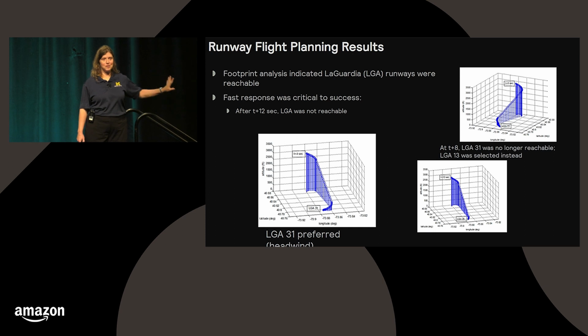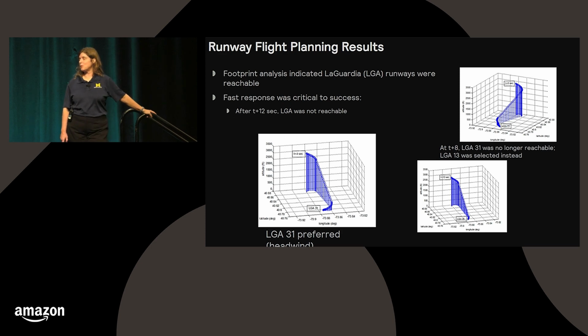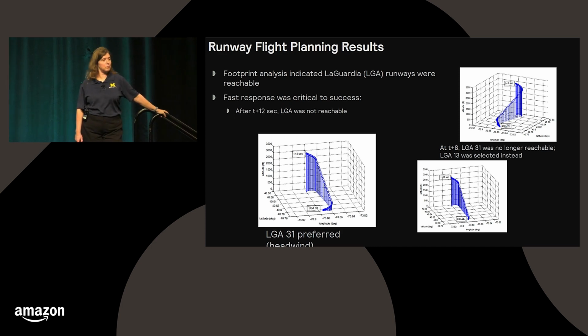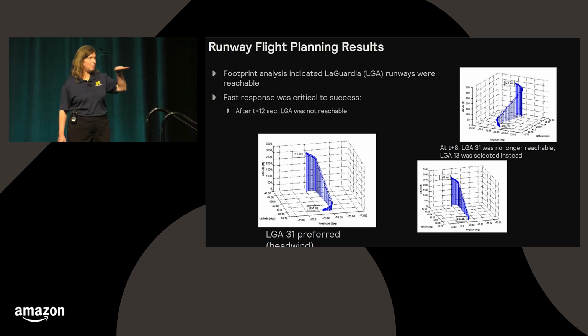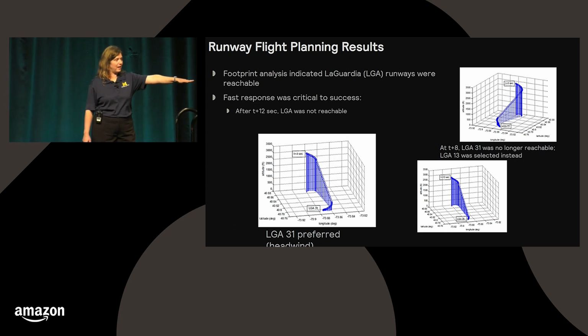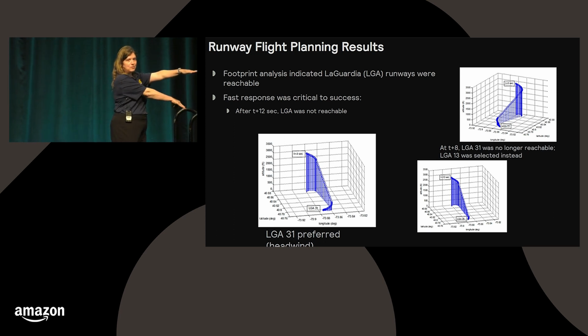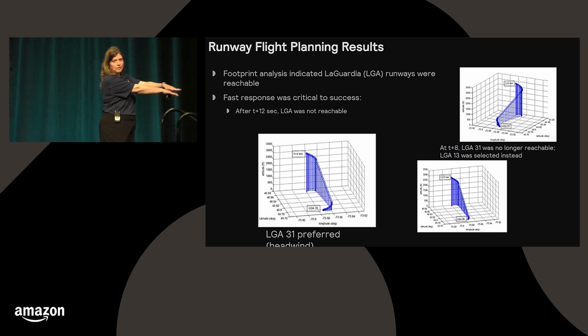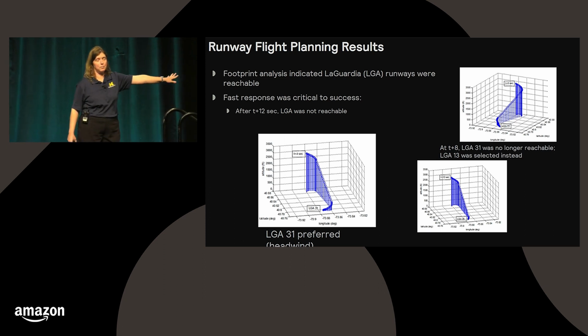They're not rooftops, but this is for all of the others, the fixed wing. So in this case, if this automation aid had been available, we probably would not have even heard about this plane, because it would have gone back and landed. And by the way, this was with a safety margin, because the way to do this is not to use best glide, which is the shallowest possible angle. The best solution is to use halfway between best glide and steepest descent, which gives you margin. So this was not close. This could have been done.